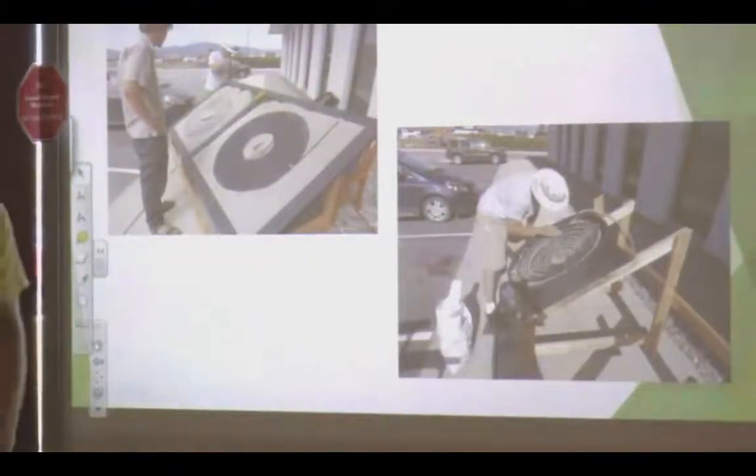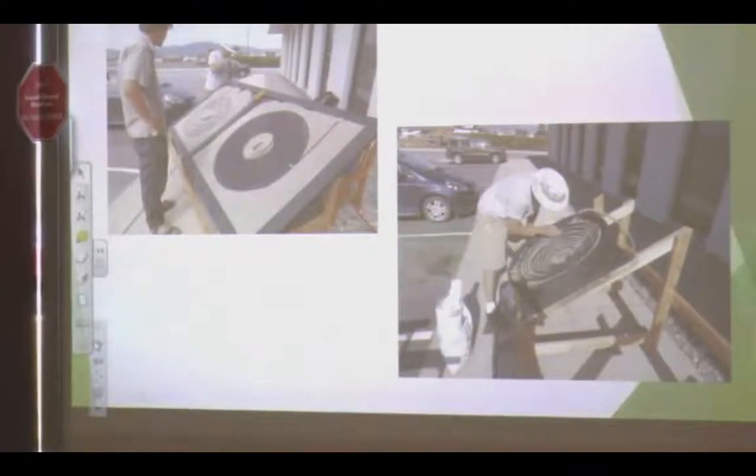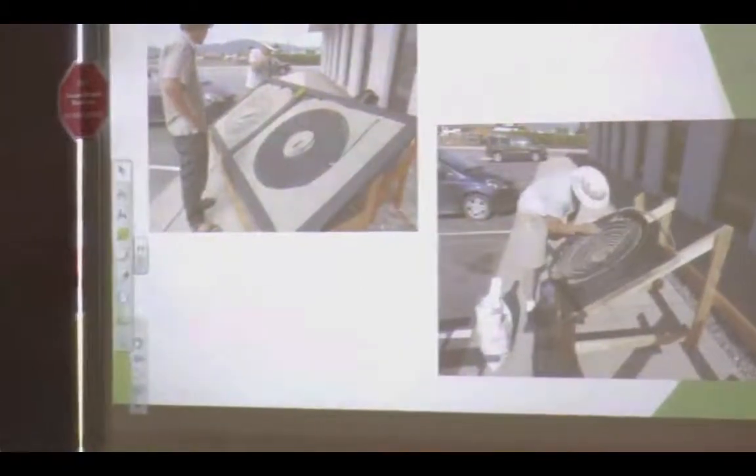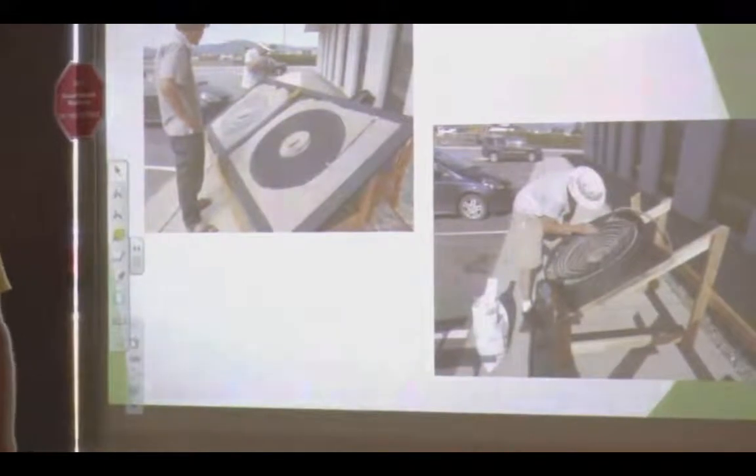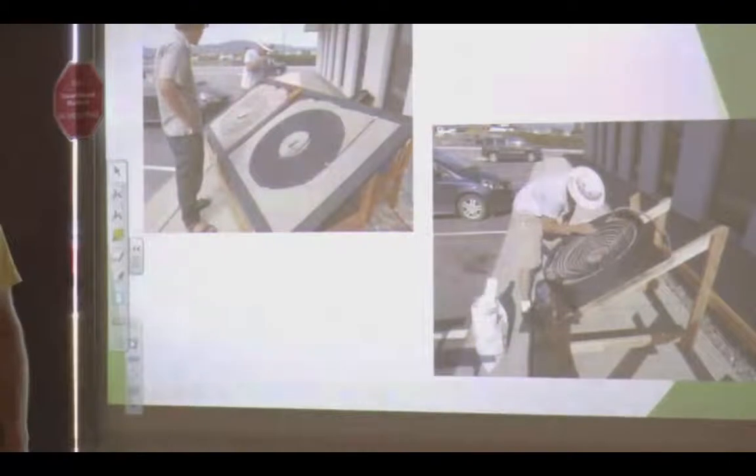So then we decided to put sand in it for some thermal mass to see what that would do. We definitely saw a little bit of a rise in all three systems with the sand in it. So that sand would heat up, and we had a lot of clouds coming through, and every time the clouds would come by, the solar insolation would drop dramatically, but the sand would continue to radiate heat to the tubing.